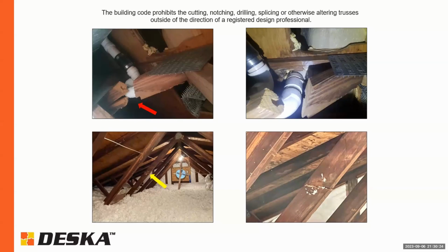That applies for floor trusses, that applies for attic trusses, and that even applies to new construction. If when they're building a home, they crack a truss, an engineer needs to essentially come up with a repair, and needs to sign off on that. Whereas the trusses are generally only inspected at the factory, but once they're out of the factory and they've left that inspection, any alteration needs to be approved by an engineer.